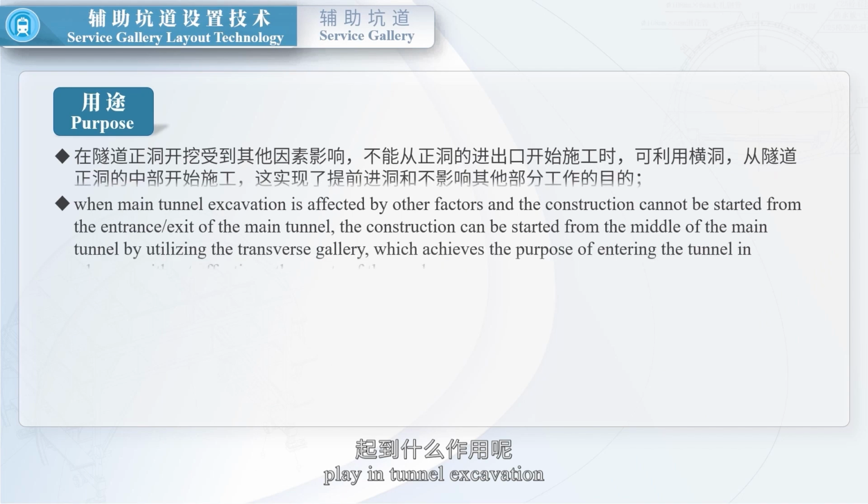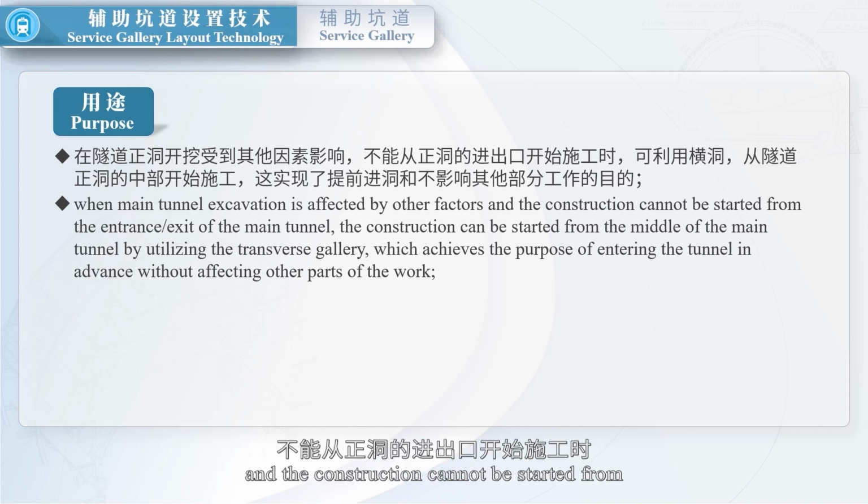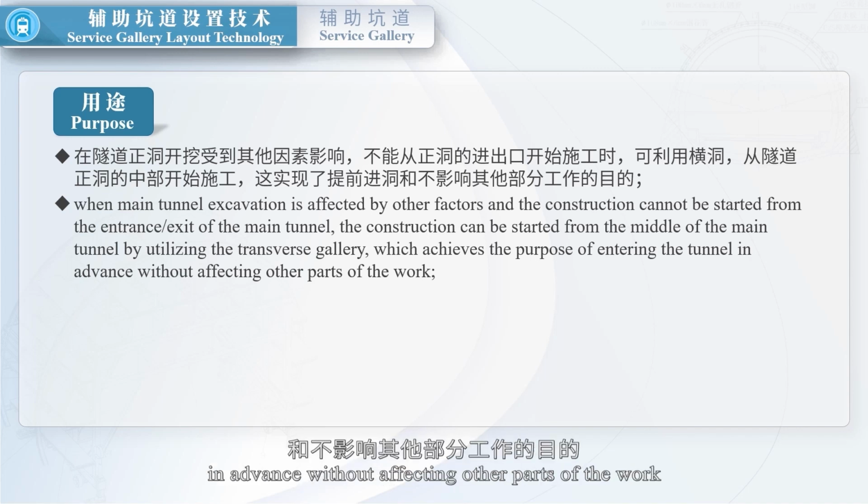play in tunnel excavation? First, when main tunnel excavation is affected by other factors, and the construction cannot be started from the entrance/exit of the main tunnel, the construction can be started from the middle of the main tunnel by utilizing the transverse gallery, which achieves the purpose of entering the tunnel in advance without affecting other parts of the work.